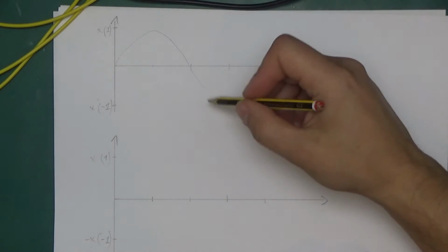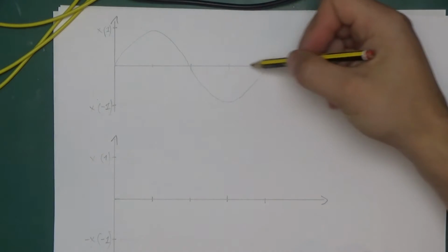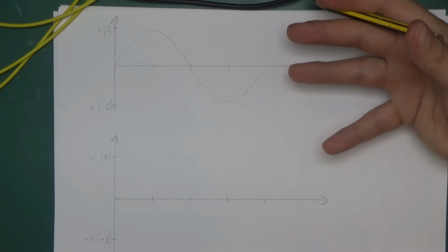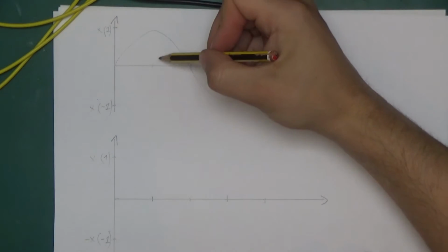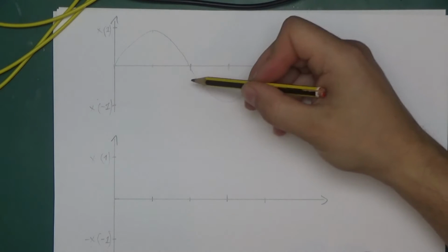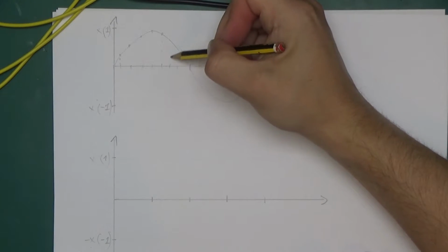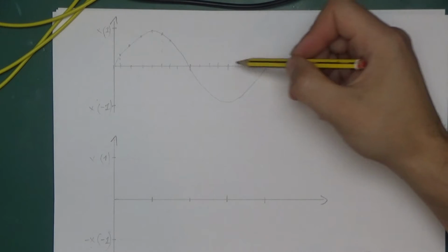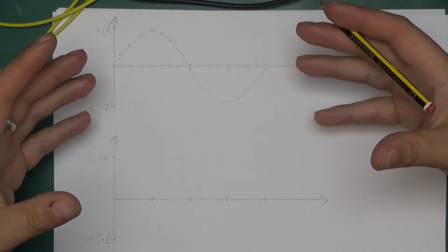There are complex ways of calculating the actual RMS value, but an easy and quick approximation is to divide this into multiple points, take individual measurements along the waveform, then do the root mean square. With a sine wave, to get an accurate reading, you would need to take quite a lot of measurements here. So at first you do one here. The important thing is that the measurements are at equal intervals. Take a reading at this point, this point, this point, this point, and so on. You get the idea. This would probably not be enough to get an accurate reading, but if you keep adding measurements in between the other ones, you probably get enough points to get an accurate reading.